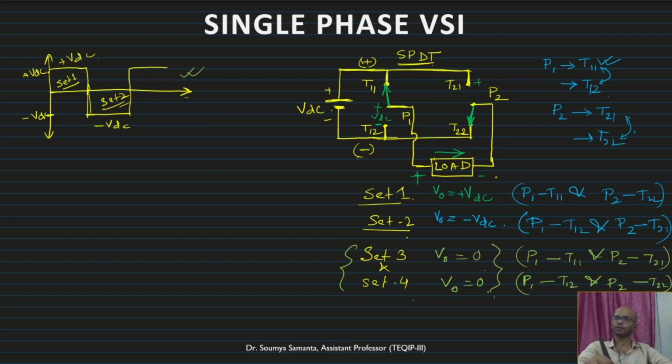Now if this is plus, this is shorted, this is minus. So this will also block the positive VDC. So under this condition, these two portions will block the positive voltage. Now what is the conduction under this case? Obviously the current will flow from positive, from this side to this side. This is the conduction. Now this depends on the load.